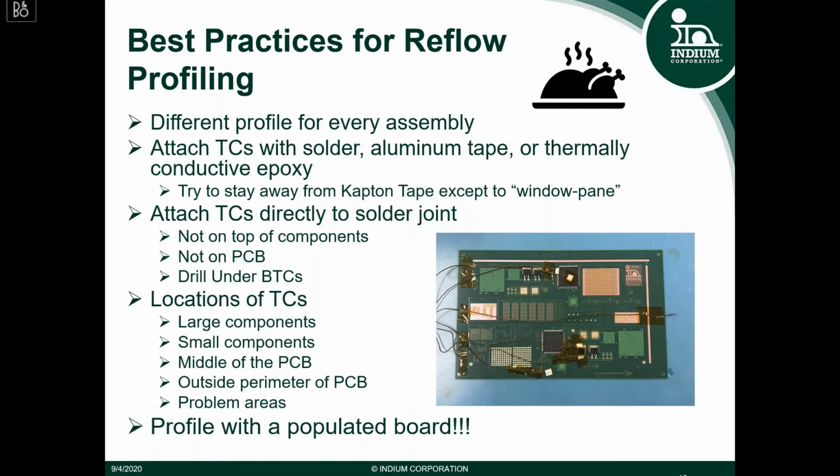And finally, the most important consideration for profiling: profile with a populated board. I can't tell you how many times I see people profiling with a bare board and it will not give you an accurate reading. I promise you, you will see a major difference between a bare board and a populated board. I know that not all components are cheap. I know not all boards are cheap.